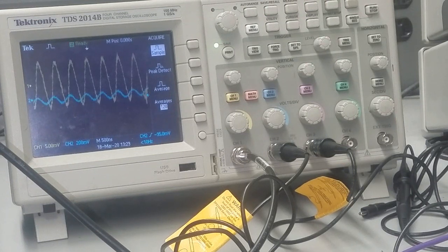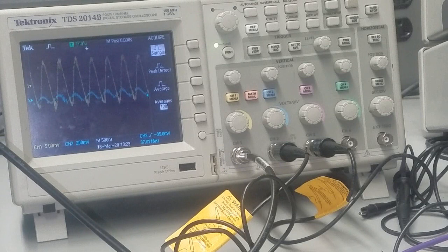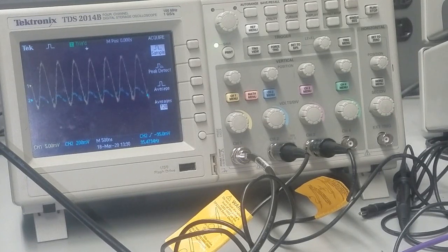Now keep in mind that our breadboard starts to degrade around 500 kilohertz, but it will handle 1 megahertz. But you can see that the response dropped dramatically at 1.4 megahertz. So clearly this amplifier has a mid-band gain, a low cutoff frequency around 40 hertz, and a high cutoff frequency around 260 kilohertz.